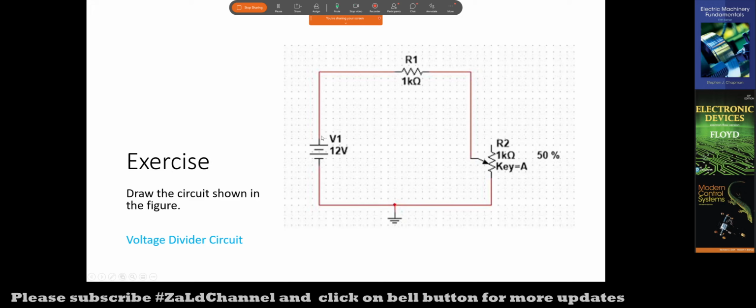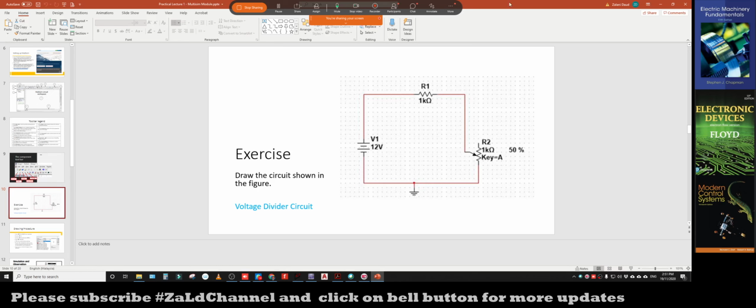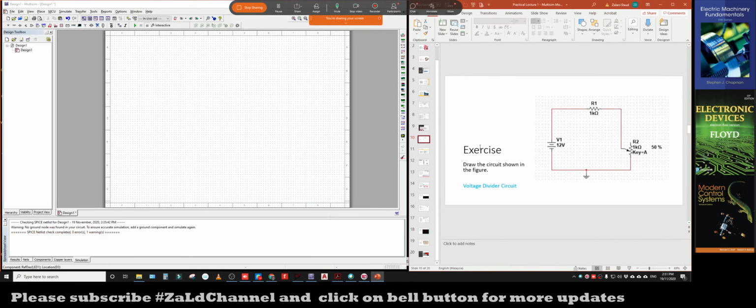And then next we are going to connect all of these components. Okay, from the positive terminal of the battery, you will connect this one to one part of the resistor, and then from this resistor we are going to connect to one part of the potentiometer. Okay, this is the potentiometer, then the ground, then back to the voltage source. So we are going to construct this. Let me just put this at the side of this screen.